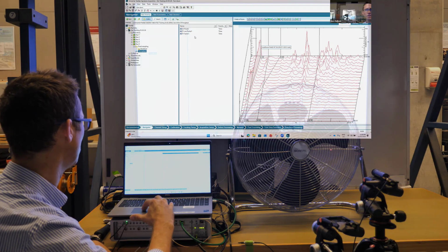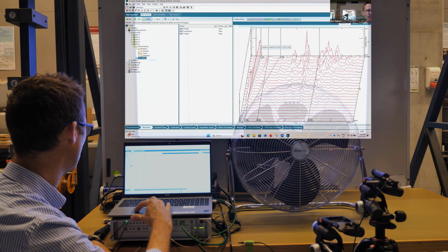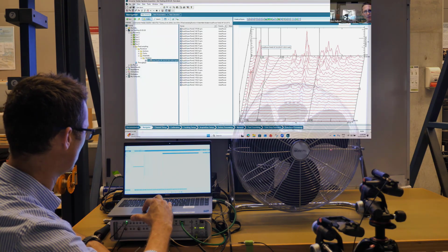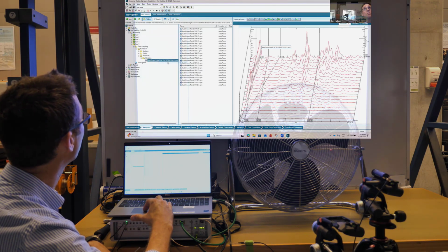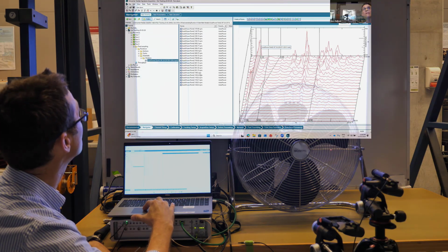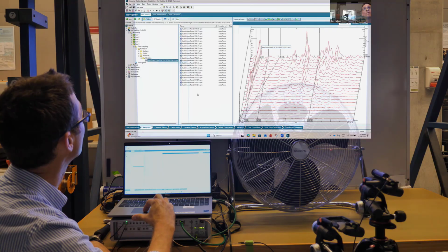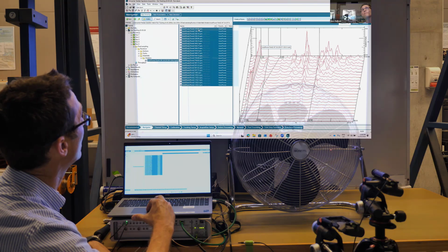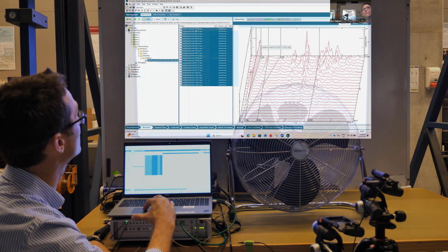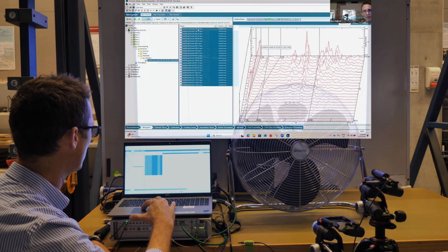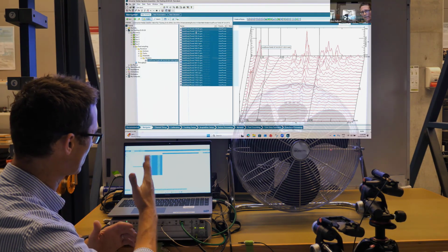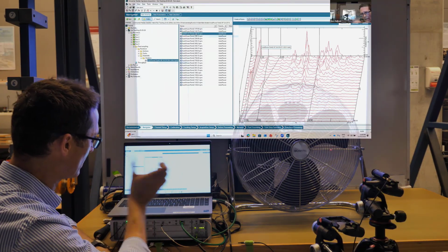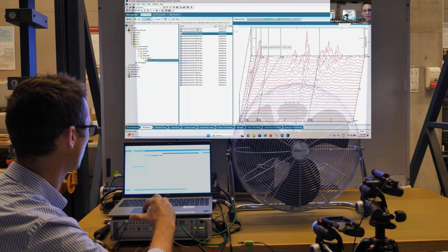Going back to the waterfall measurement, this is the collected FRFs. You can see them here in this display. If I drill through to the auto power here, there are those 20 or so, 24 FRFs at each increment given here, which is an approximate RPM for the target RPM. So it's not always the case that we get exactly 100 RPM. It's 107.69, and that's the center of the RPM. So the data are collected either side of this particular RPM, 100, 150, etc.